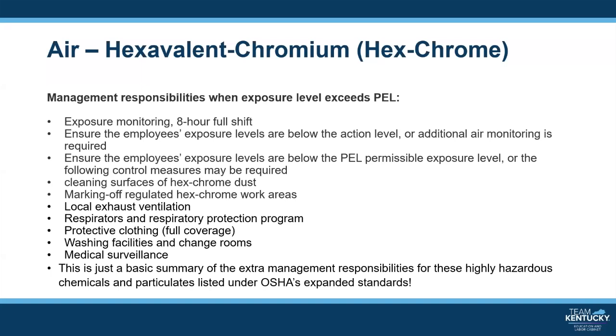This would require exposure monitoring over an 8-hour full shift workday. They must ensure that the worker exposure levels are below the action level, or if not, then additional air monitoring would be required. Management is required to ensure that the employee exposure level is below the PEL, the permissible exposure level, or the following control methods may be required.